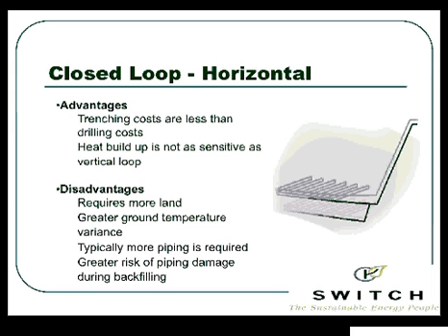It's more noisy anyway. The more air that goes through that piece of pipe, the more air noise you're going to have, because we're moving at a faster speed through the pipe. So the potential for that whistle is going to increase. It's already noisy to an extent, but if I keep pushing more and more air, you'll get to where you hear almost a whistling when it comes on.